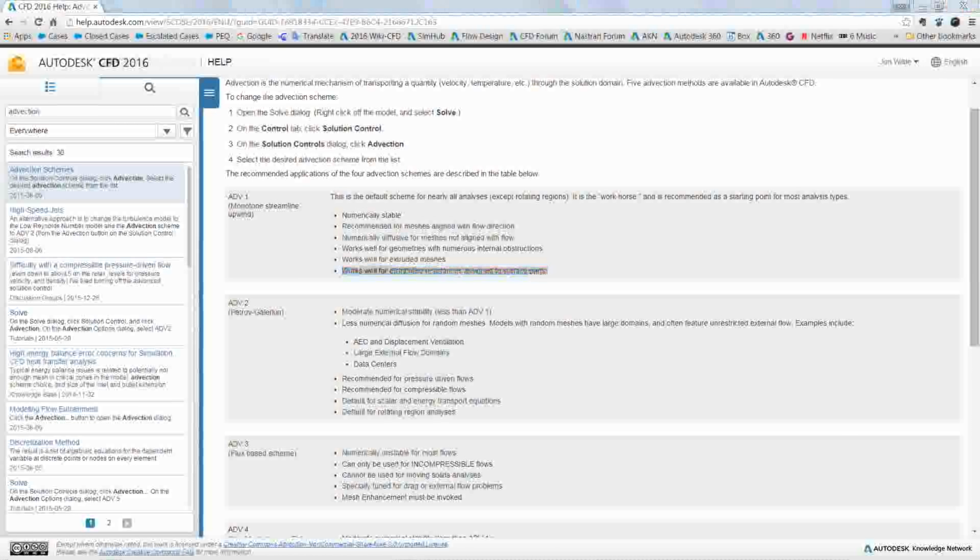Then we want to make sure that if we've got a specified pressure drop that's supposed to be happening from that resistance, as we go through, we see that that pressure drop happens. So you want to have a node inside the resistance that we can check versus a node outside. And then we want to do the same thing leaving the resistance. So you really want to have 5 nodes across a resistance, just so that that internal node isn't being used for both sides of the resistance.